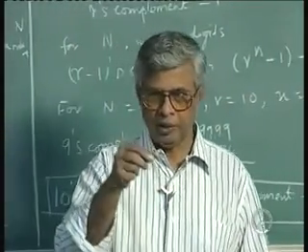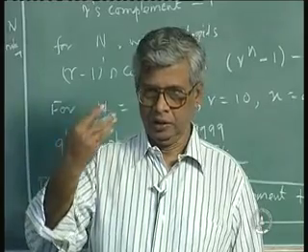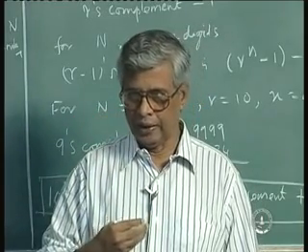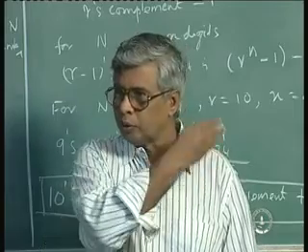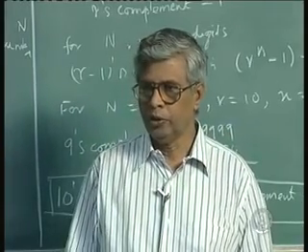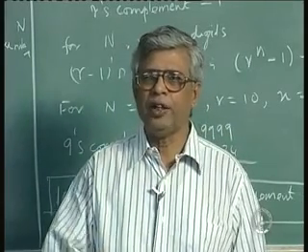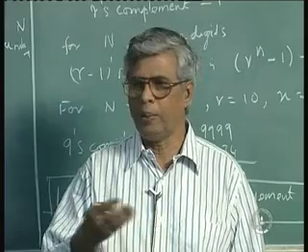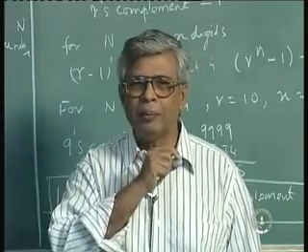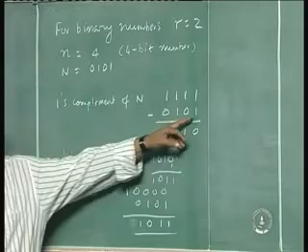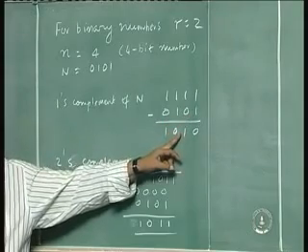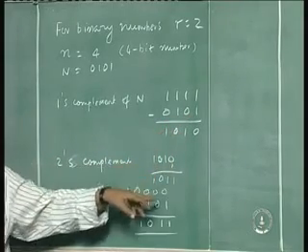So when you do subtraction by the complement method, I can show that the same adder can be used to do subtraction. That is the object of the whole exercise now. So a given number, you are asked to find the 2's complement, 1's complement, no problem. You complement the given number bit by bit, you get 1's complement. Add 1 to it, you get 2's complement.